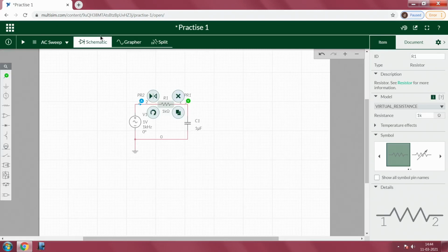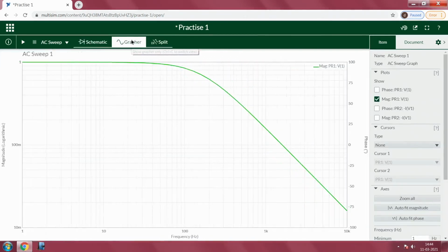When we calculate the cutoff frequency, we got around 159 Hertz. So, even from the analysis we can clearly see the cutoff frequency is close to, yes, this is 1 dB, 2 dB and 3 dB, 158.49, and we calculated 159. That is theoretical versus practical. I hope this is clear for you to understand how we can use an online multi circuit simulation software for analyzing our circuits.